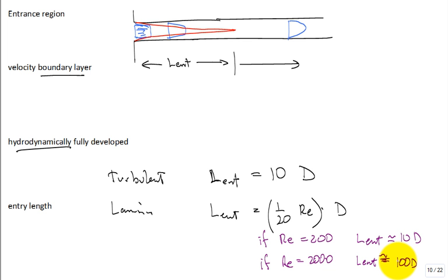All right. Where is this practically important? A lot of times they'll have piping systems, and somebody will say, I need to stick a flow meter into the piping system. But the flow meter is anticipating fully developed either turbulent or laminar flow. Almost always it's fully developed turbulent flow that it wants, right?